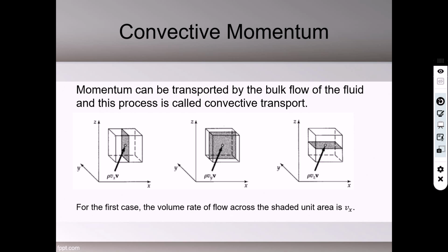But in fluid, especially for the stationary flow, you actually do not have the velocity change, but you have the mass change, because mass goes in. So you don't have the term which gives you the ma, but you have this term because the fluid always flows in that way. So dm/dt is your mass flow rate, right? So it's this term multiplied by v.